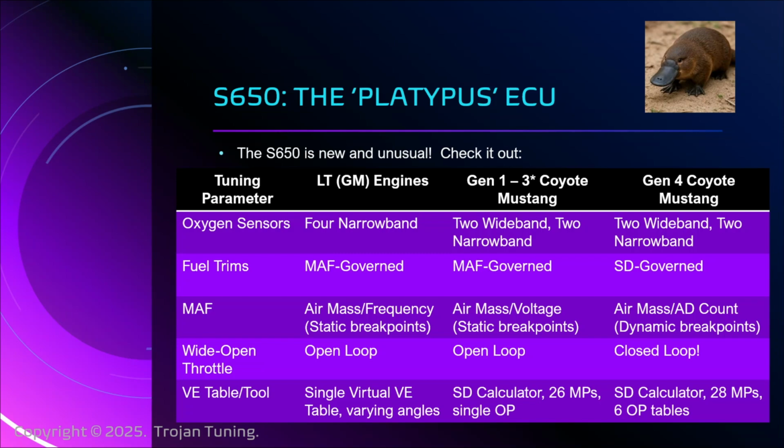And in well-engineered systems, you will always have redundant checks going on. You will see later on that the torque calculators are something we must understand fully, because the torque calculators are constantly monitoring and can clamp down at any time. But basic running around town, it's the MAF that's calculating most of the air.